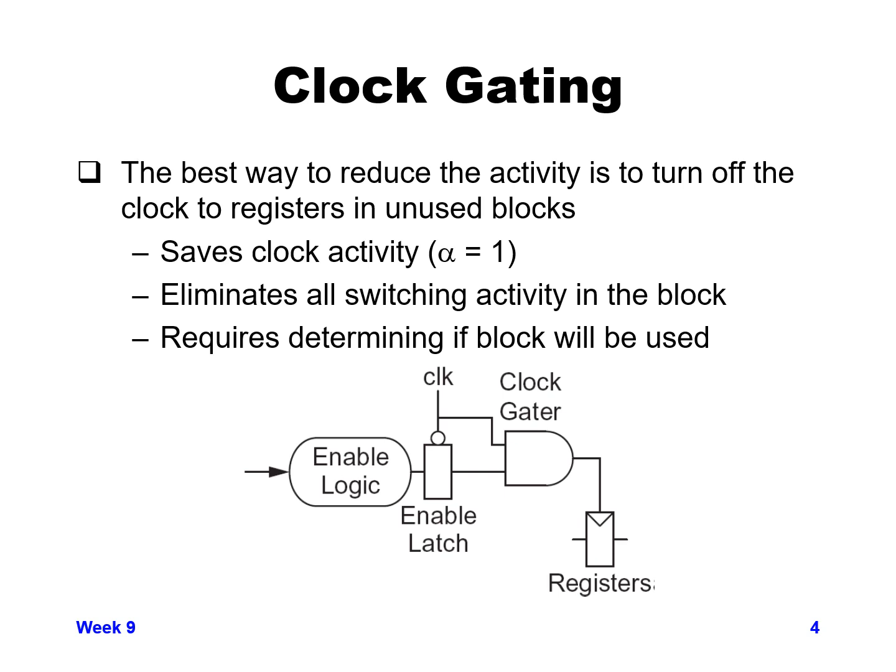So one of the ways that you actually can, and is actually the best way to reduce your activity factor on average, is to pay attention to when your logic is actually being used versus when it's not being used. For example, if you have an ALU and you're not sending any function to the ALU, you're not doing an add or a subtract or a multiply or whatever other functions you have, and you can see, possibly even in your pipeline, you can look ahead many different functions and say, oh, I'm not going to use this ALU for 10 cycles.